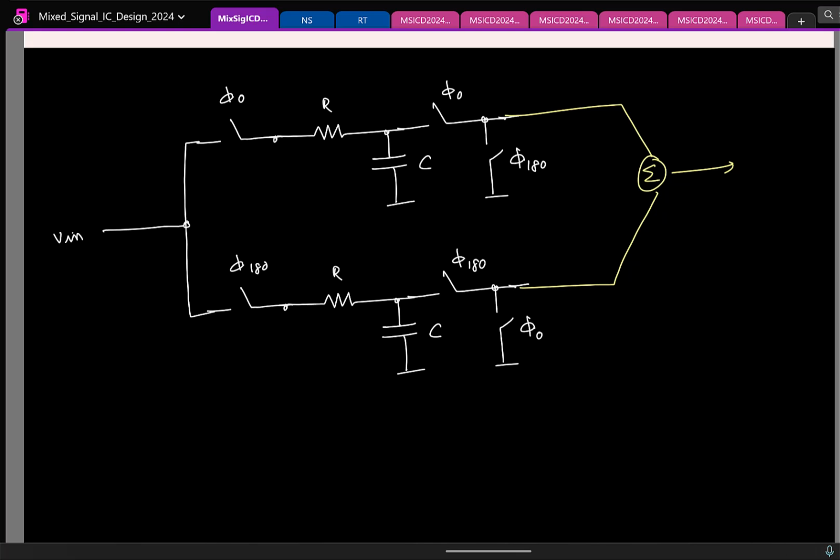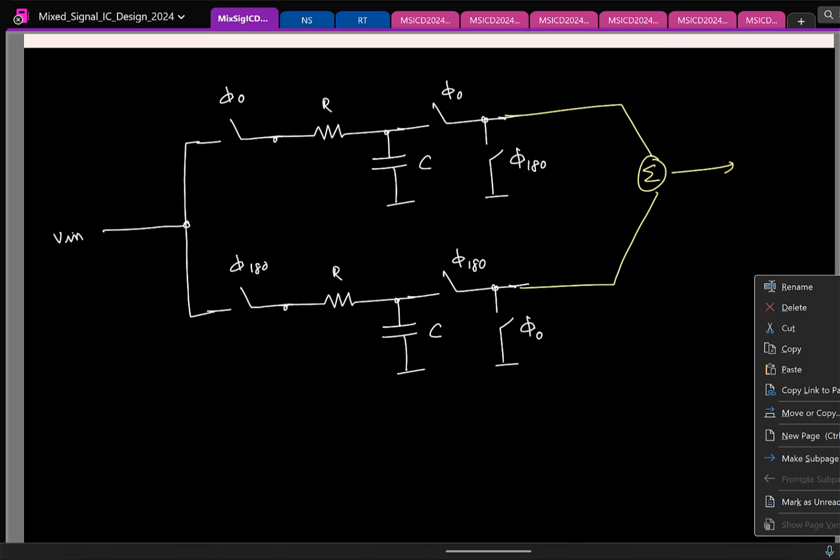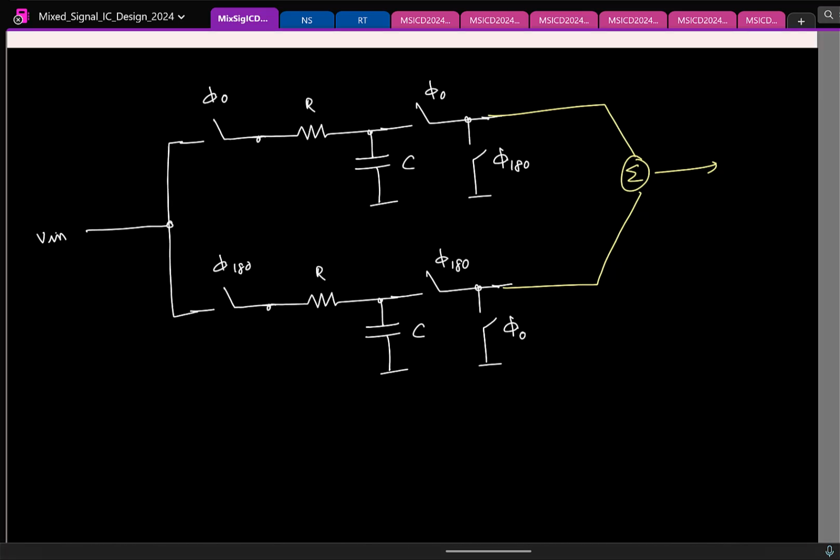If I do this, hopefully the amount of aliasing reduces. Earlier, let us say there were 1000 frequencies that were aliasing. Now if I do this, how many frequencies do you think will alias? Less, but can you give me a factor? We are increasing the sampling frequency by 2x, so the number of things that can alias back will halve.